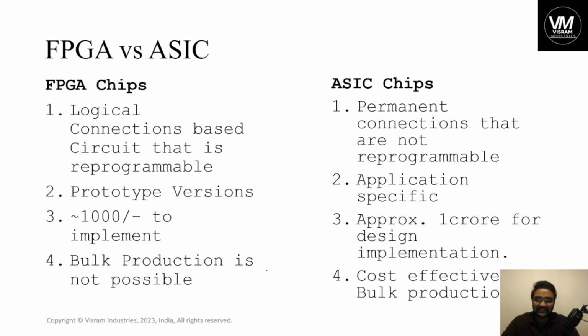As I said, in an FPGA you can use a group of logic cells, reset them, and use another group of logic cells. But in ASIC, every logic cell you implement in the design, you place and route with connections, and those are used in that particular way. You can't increase or decrease the count of logic cells. So ASIC chips are made with only a specific number of transistors or standard cells. So those are not reprogrammable.